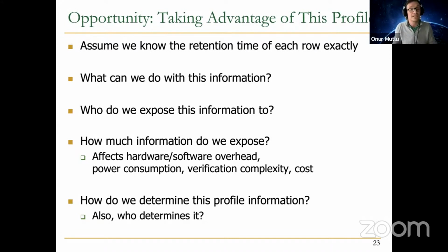It may retain data for only 16 milliseconds. So this is a problem called the variable retention time problem. I like thinking of it as a quantum-like effect in modern circuitry. It's not predictable. This process is random. And randomly, a cell's retention time changes.